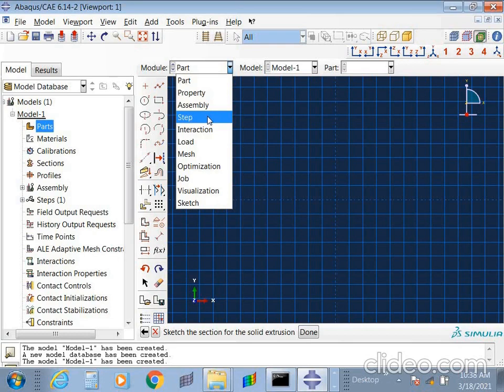Okay, and step interactions in the sense, in this interaction you will have all the types of contact generation or interaction, predefined loads or predefined structures, whatever extra loads or point loads need to be added or connecting points, everything will be stored in the interactions. Whereas load, you know that load and boundary conditions, point load, pressure load, any loads will be in the load module.